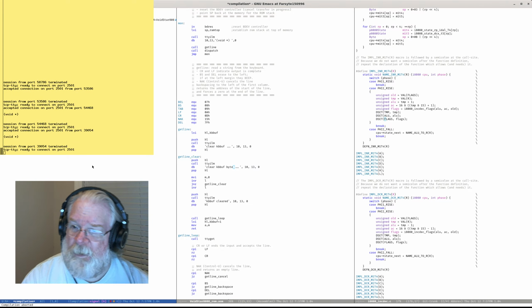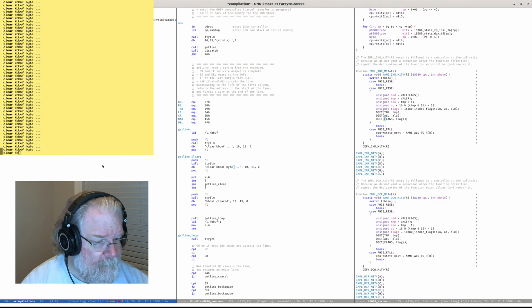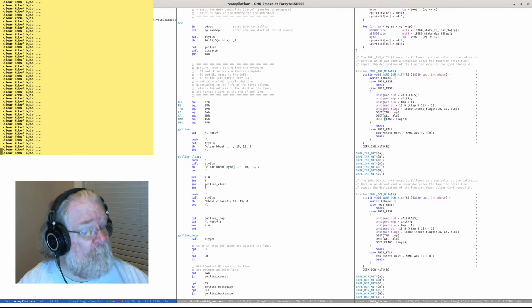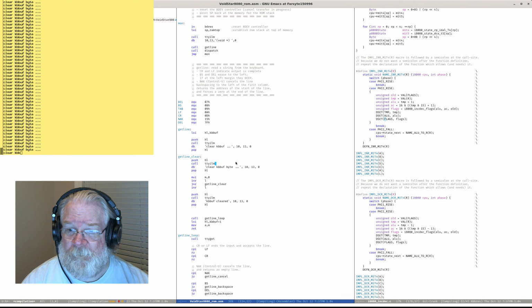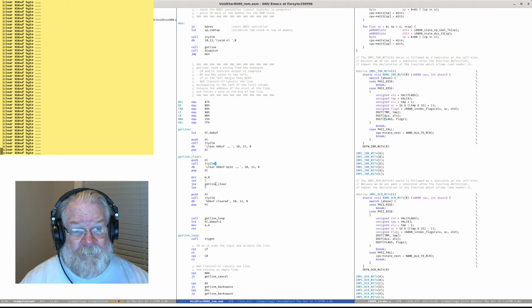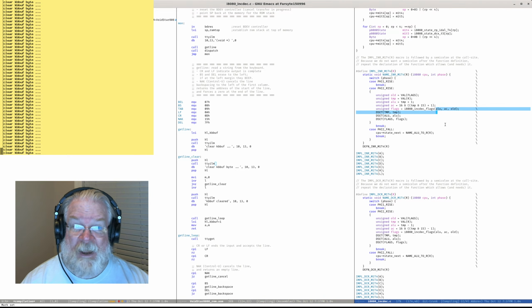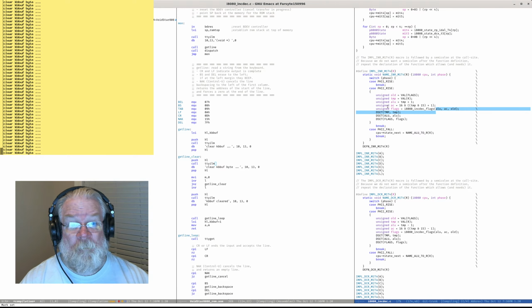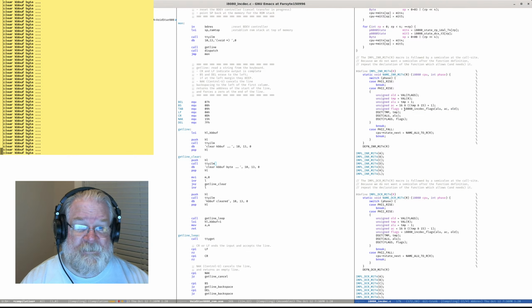I have to redo this twice. First time I do this, it's just too fast to reconnect. So you notice what's going on here. We are clearing KB buff byte over and over and over again. What this means is that INR is not properly setting the Z flag. Now I think I know what's going on here. I think we are handling an ALU flag to DEC flags, which is 8 bits, but it's actually more than 8 bits and it has 256 in it. So we just found a bug in the INR instruction.